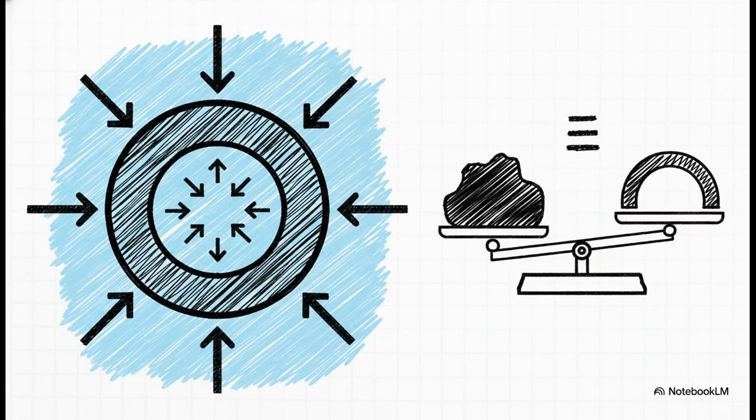The main job is getting the product down safely. You are constantly playing this intense balancing act between the massive top tension required to hold the pipe at the surface and the severe bending stress at the bottom where it actually touches the seabed.